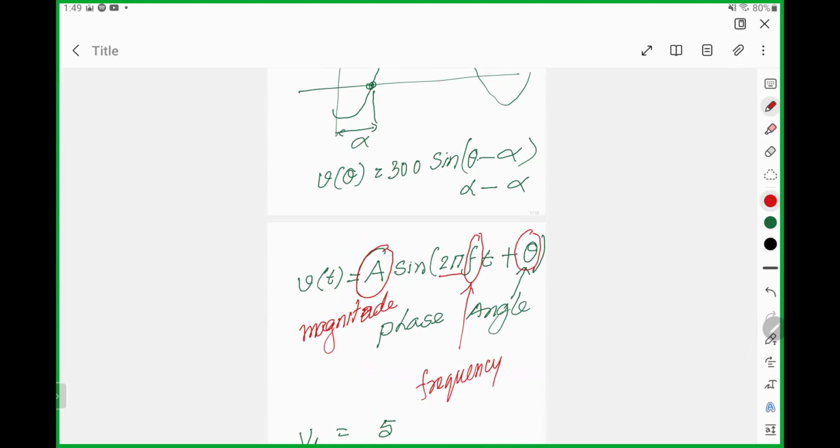So phase shift is the third property. Now, if you don't change this frequency, say for power engineering we are not changing the frequency, right? Then this part has no impact on my sinusoidal signal because you are not changing this frequency. But this phase can be changed.